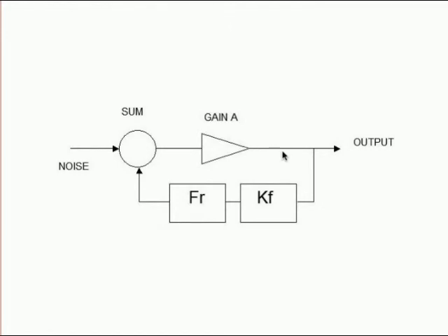Now we need to consider how this will differ from a practical oscillator. Well, if we've got noise coming in at the input, passing through the system, being filtered and coming out at the output, we can look at this in terms of AM and PM sidebands around a carrier. So it means that the AM and the PM sidebands will be processed identically.